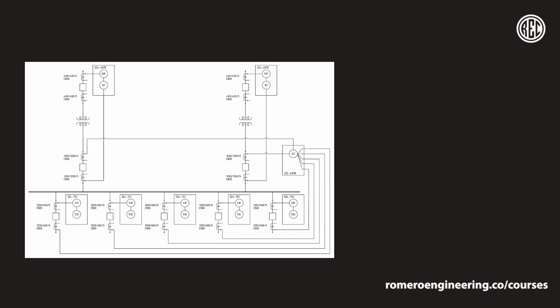Now, these errors can be very small or large depending on many factors, such as the fault current levels, the type of CT that you're using, the accuracy class of the CT, and so on and so forth. So we need to develop some form of 87 or current differential algorithm that takes into account this realistic but non-ideal behavior of the CTs.